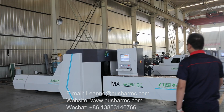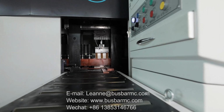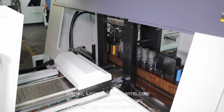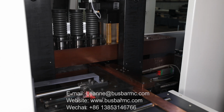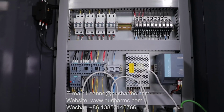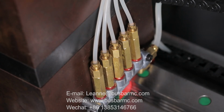The bus bar machine consists of the following parts: a loading table with stainless steel rollers, a single row in-line mould library for left and right position movement, a hydraulic clamping system with position detection, an X1 servo shaft for front feeding, and a rear-end pulling X2 servo shaft, finished stainless steel conveyor belts, electrical control system, hydraulic system with proportional valve control and automatic lubrication system.